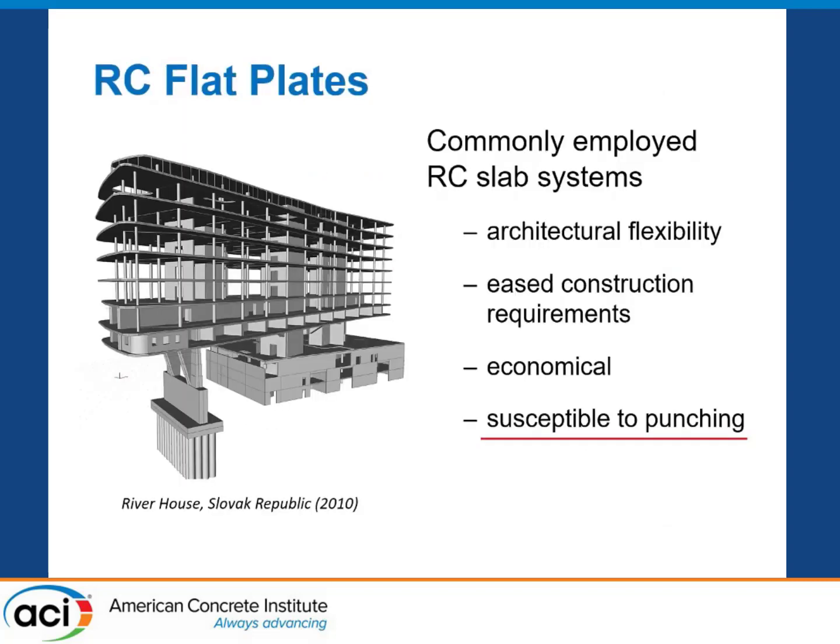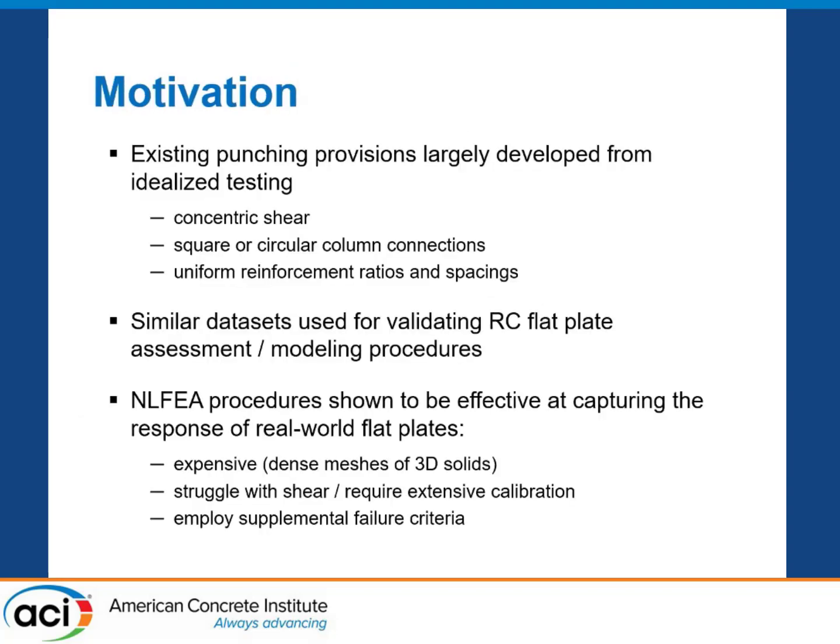RC flat plates, I think we're all quite familiar with what we're talking about here, but obviously a very popular option in North America and much of the world for a number of reasons. Very flexible, very good for construction, cost effective. Unfortunately, kind of the Achilles heel is they're more susceptible to punching, right? That's kind of their primary drawback if you were to think of only a few.